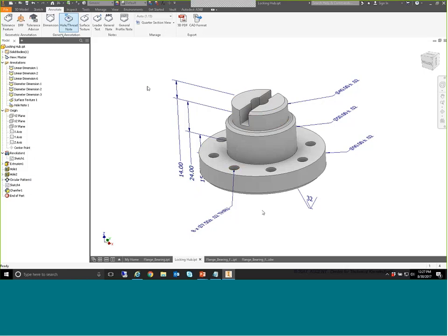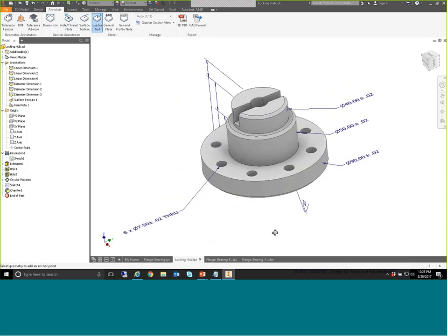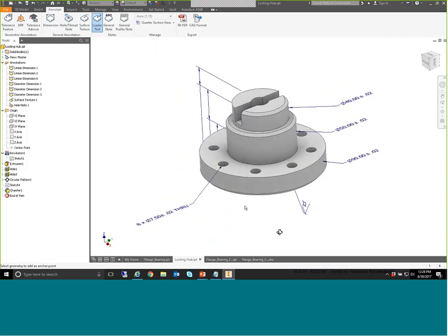So finally, we've talked about all of the general annotations, so the dimensions, the hole thread notes, the surface texture. I talked a bit about the 2 other 3D annotations that are text-based, the first one being leader text. So we'll deal with that one now. So I've just selected the leader text option. And one of the first things that I noticed is that there is no 3D annotation for chamfer notes. So this is a bit of a workaround for incorporating notes on chamfers.